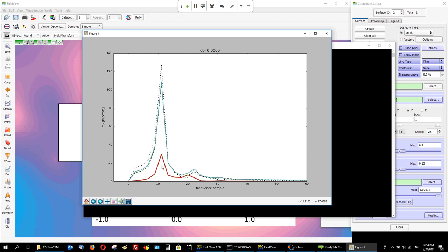You will see frequencies, for instance, present in different areas of the region, like the turbulent boundary layers will typically be very frequency rich. And what this plot provides as a benefit is that, thanks to the magnitude, you can really discriminate which are the most significant frequencies for the flow you're working with. Didn't mention it here, but each line is for one point on which we've followed the CP variation over time. So you could add more points to the script, and the location also was hard-coded, but it will be easy to change that or do it for any location that you're interested in.